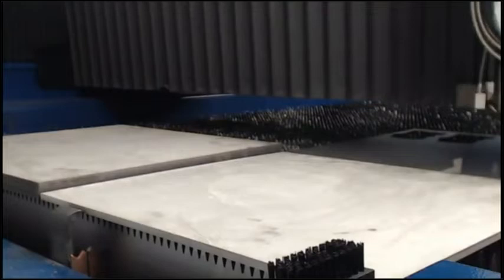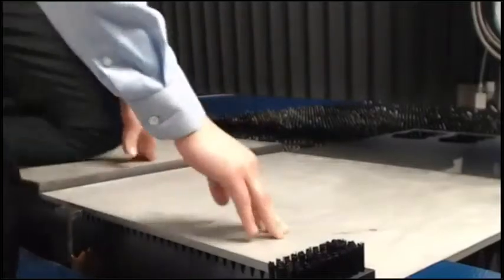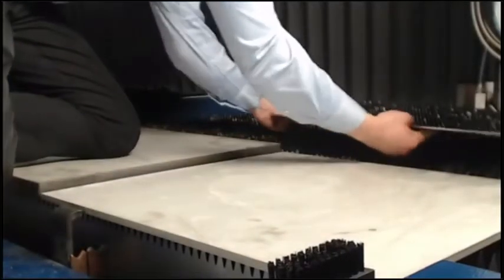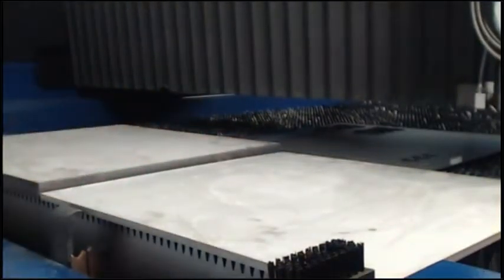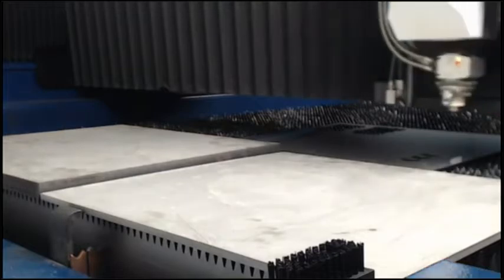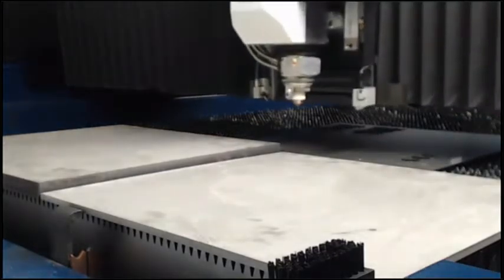So what would be interesting while James is changing that position, what's cool about cutting with compressed air with the high-speed Eco nozzles, and indeed really with a dry air assist system, is it really is extremely close to what you would have as a parameter set for nitrogen. So if you said, okay, I've got one of the Trump machines and it's got high speed, it's got Highspeed Eco, but I don't have tables for 1/4 inch steel with compressed air. Well, you can simply create a copy of the nitrogen table, just change the assist gas, and you might slow it down a little bit, you might not, just judge it based on what the results are, but they're actually extremely adaptable.